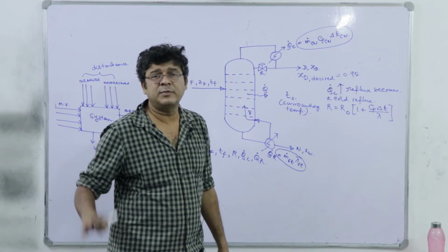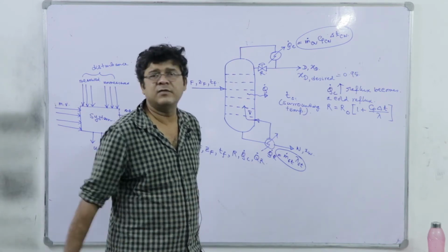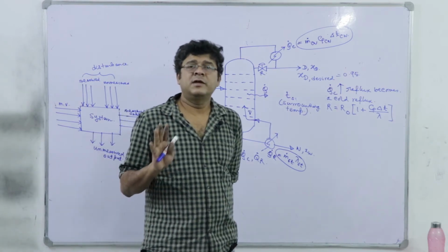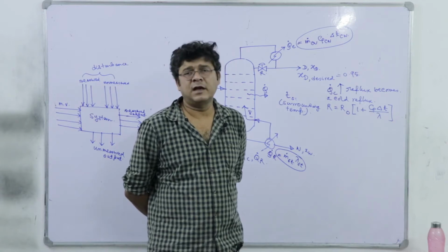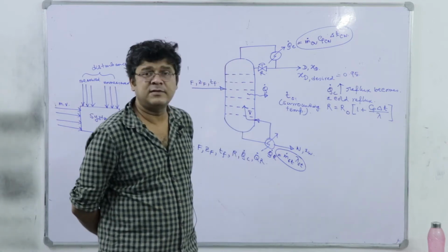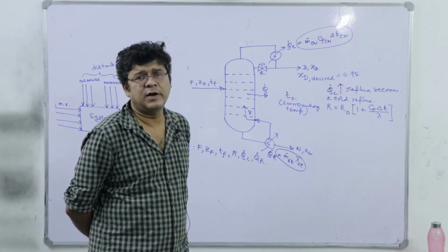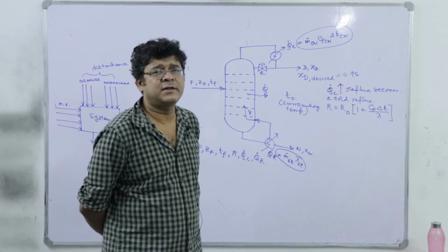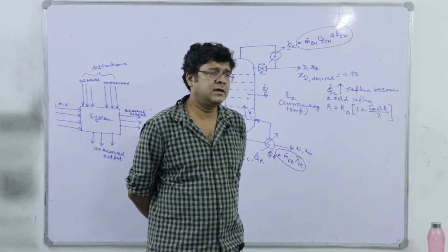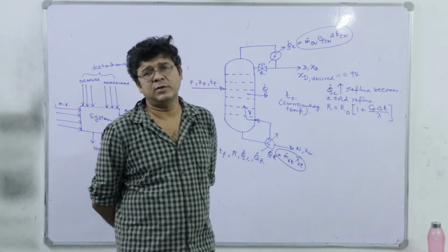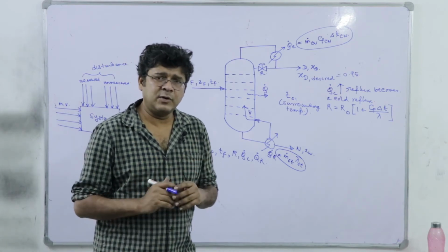Don't think of it from the perspective of a design problem. In a design problem, as we have mentioned in several other subjects, the input and output will be given, but the device is unknown. Like here, the number of stages of this distillation column is unknown and we have to calculate it. So we use either Lewis-Sorel for analytical calculation or McCabe-Thiele, under the assumptions of equimolar overflow and equilibrium stages, and we calculate the number of stages. So that's a design problem.